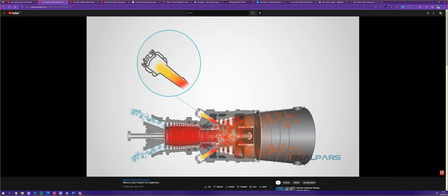There are different technologies in properly mixing the air and gas and making efficient combustion from manufacturer to manufacturer. Combustion chambers are of some tubular heat-resistant structures, and fuel is usually injected into it from the circumference and at different cross-sectional locations. The temperatures at different locations of the combustion chamber are thoroughly monitored by means of proper sensors like thermocouples.